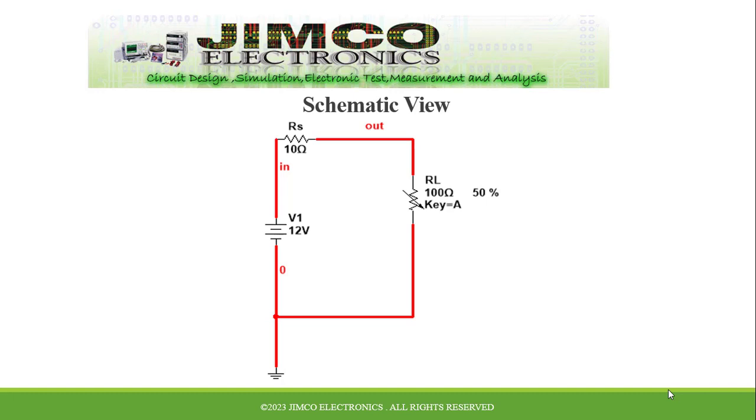In a communication system, the radiation resistance of an antenna must match the output resistance of the radio transmitter. Another area of application is in designing amplifier circuits. For instance, a class A amplifier needs the output impedance to match the load resistance for maximum power delivery.